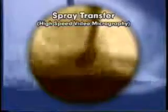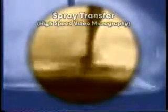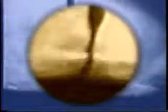The spray transfer mode deposits small droplets of metal at rates of several hundred per second. Spray transfer requires high electric current and argon or argon-rich gas mixtures to shield the arc. Metal transfer is stable, directional, and virtually spatter-free.